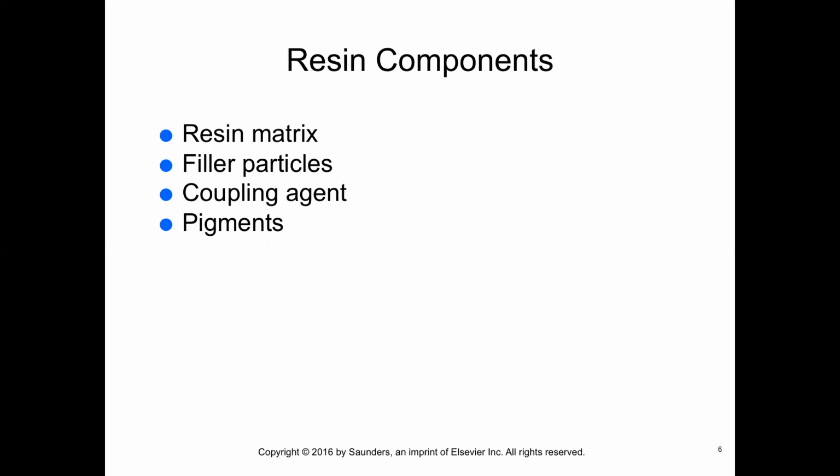Monomers make up oligomers and are organic molecules with double carbon bonds that link together by an addition reaction to form a polymer. When the polymerization reaction goes to completion, the result is a cured composite resin. Filler particles are added to the organic resins to make them stronger. Fillers are also added to control handling characteristics. They help to reduce shrinkage and are used in composite resins made up of inorganic particles such as quartz, silica, and glass. The higher the filler content, the stronger the material will be.